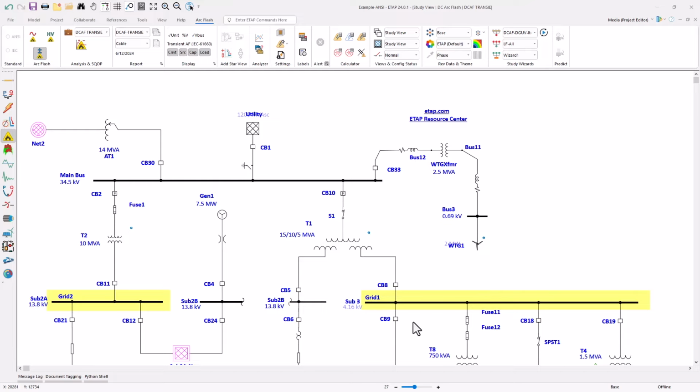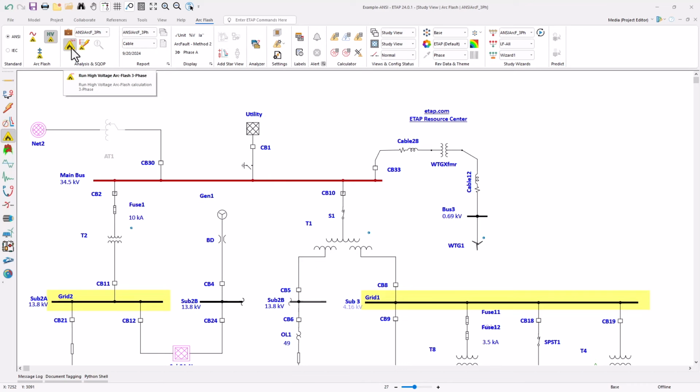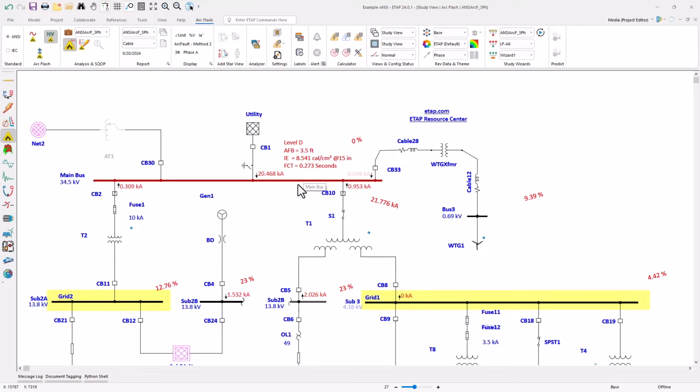The next ETAP ribbon bar feature offers intuitive and easy to understand display settings without opening its interface every time to change units. As an example, if I run an arc flash study beyond 15 kV where we have distributed energy resources like wind turbine generators or inverters, which definitely provide a proper voltage ride-through capability based on the IEEE 1547 standard that requires to have a proper stability to the grid, they all basically rely on the bus terminal voltage.